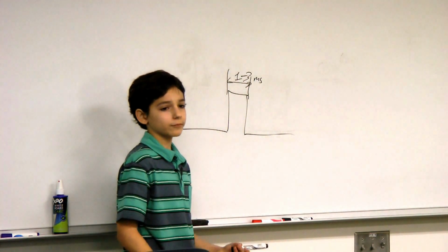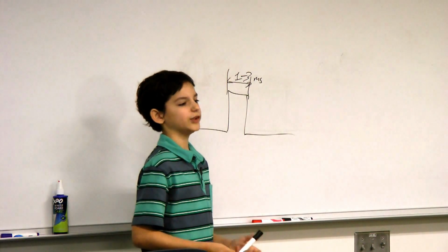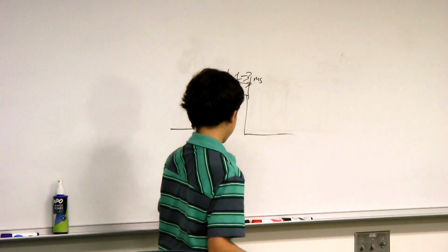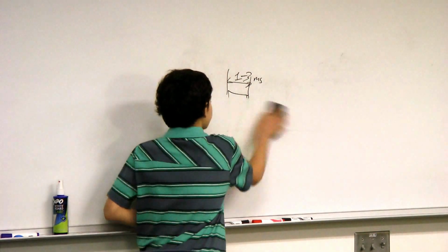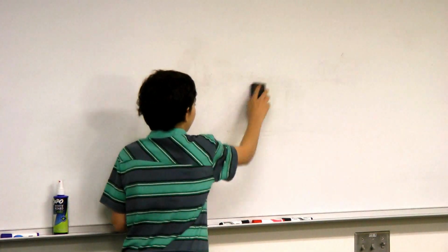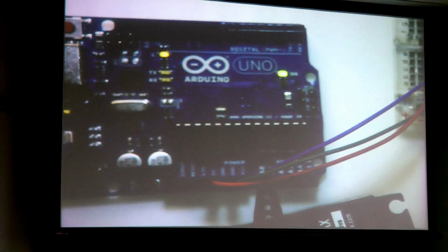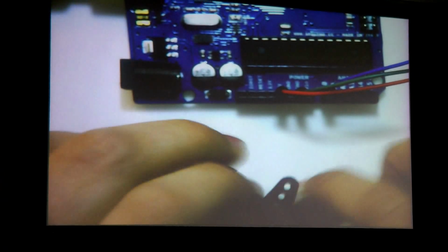Or some servos support PWM, so that's another option. It just depends on what you do. In this case, I'll use the servo library. The servo library also handles sending out a new pulse to the servo every so often, I forget exactly how often, so the servo keeps its position.